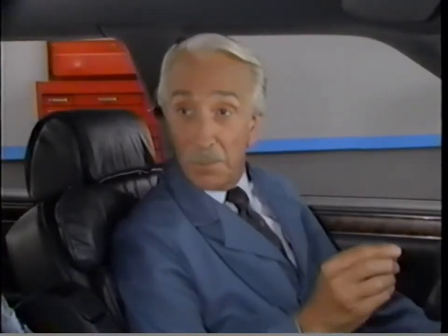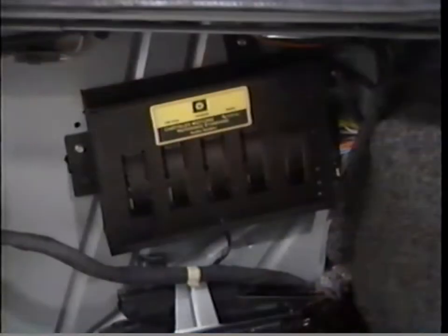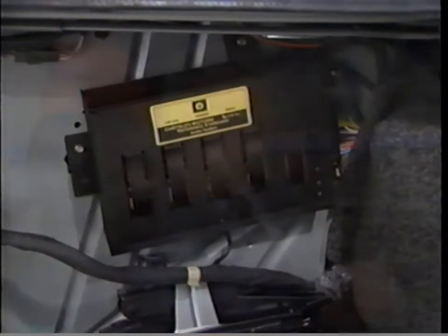Okay, so now by adjusting the fader knob, we've narrowed the problem to one front speaker. On the RS system, the speakers are driven from the amplifier located in the trunk. So we'll have to check the connectors from the amp to the speaker. On all other Chrysler systems, you would check the connectors in the rear of the radio. You'll have to check the vehicle's wiring diagram to find out where these connectors are located and their pin locations.